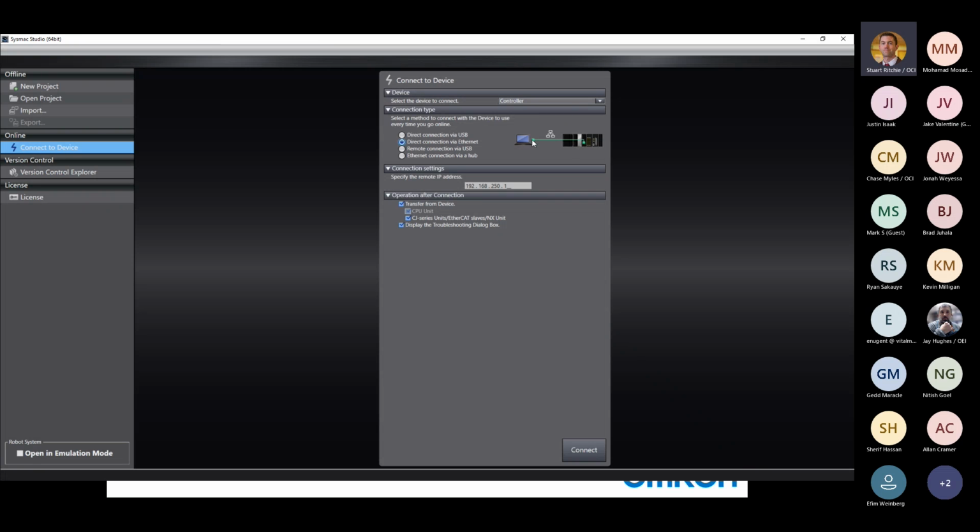The important thing here is there's no network infrastructure in between the PC and the PLC. Some unmanaged switches will let it happen, but it's kind of a broadcast protocol, so managed switches often don't let that through.